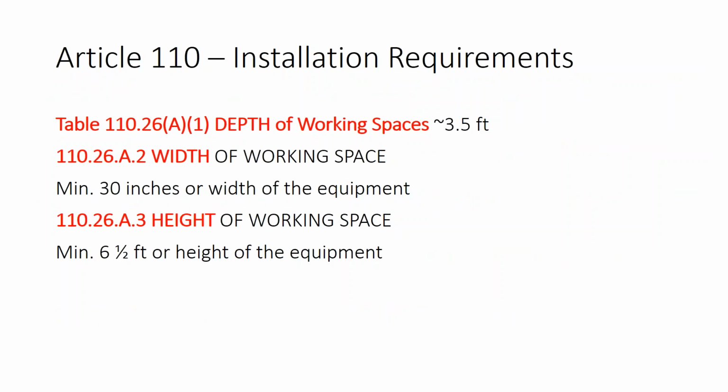There are rules in code pertaining to the layout of electrical equipment. In general, you're not supposed to combine electrical spaces with other work scopes like plumbing or air conditioning. And by spaces, I mean the square foot distance. So you can have rooms that have multiple scopes in them, but if you mount an electrical box on a wall, you're not supposed to run plumbing right across that same space.